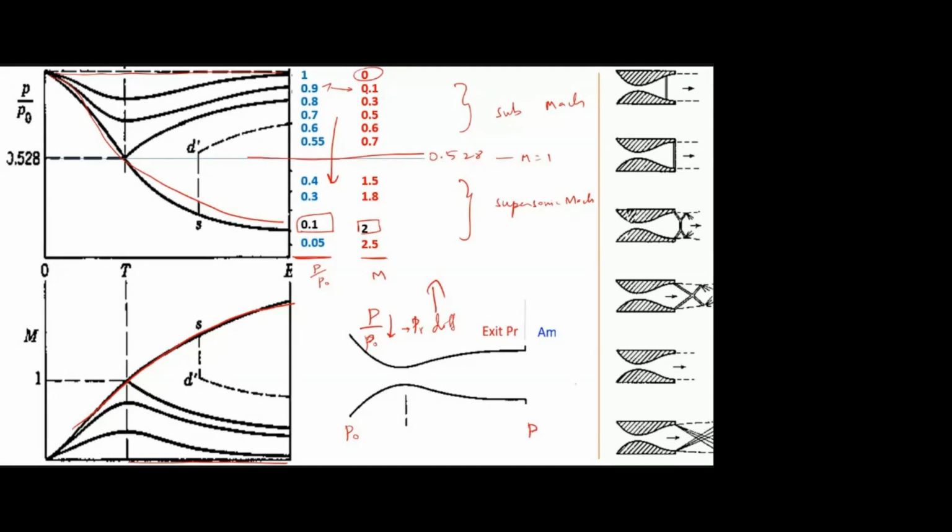So what will happen because of this increase in pressure difference? The flow will accelerate a little bit up to the throat section. This is a convergent nozzle, right? So subsonic flow will get accelerated in the convergent duct, up to a maximum at the throat. Again, this is a divergent duct, so subsonic flow will get decelerated in the divergent duct. So you can see the Mach number is accelerated up to the throat section, that is the convergent duct, then from there it decreases again to the Mach number of 0.1 for the pressure ratio of 0.9. Is it clear?